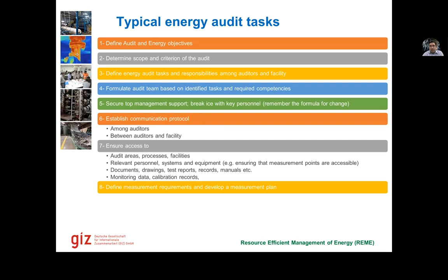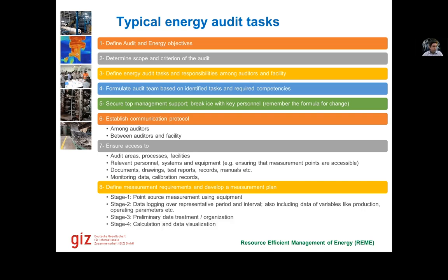Then defining what kind of measurements do we need to do more. So after having this data, we need to see, okay, what do we need to measure? What are the areas we need more detailed planning and measurement? So there are different stages to it. For example, we could do a point source measurement, for example, stack analysis or measuring the energy profile. Stage 2 could be a data logging.